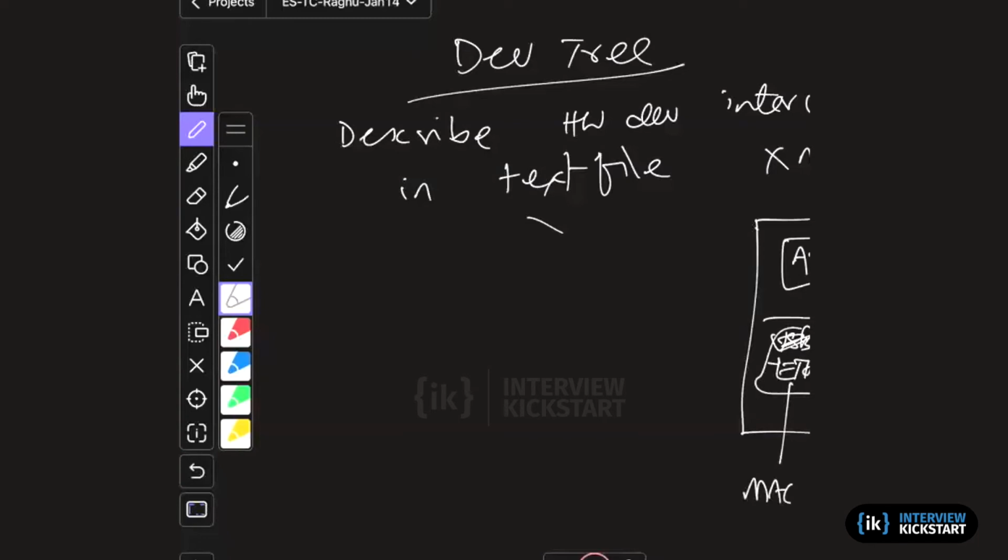So the device tree source file, basically a DTS, will try to capture this information in a particular syntax. I am not going to go into the syntax, but it generally says something like CPU. You can give it a name, CPU 0, CPU 1, and then you describe what kind of clock it will run, an entry, whatever address, and so on.